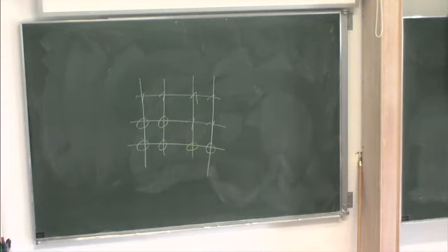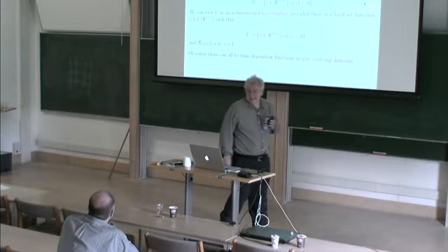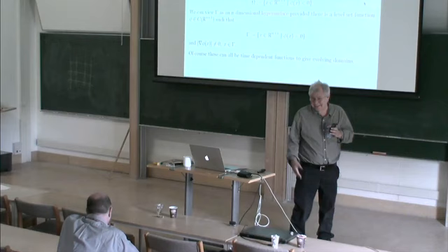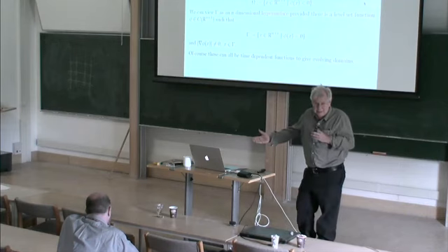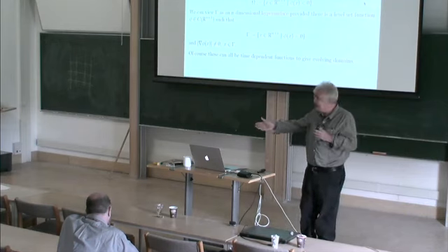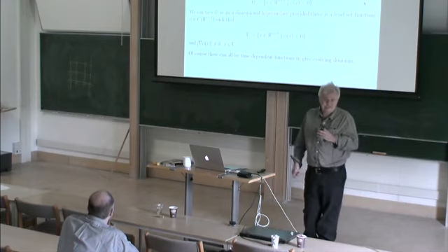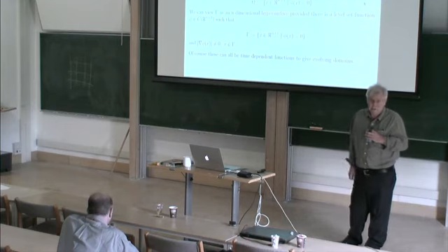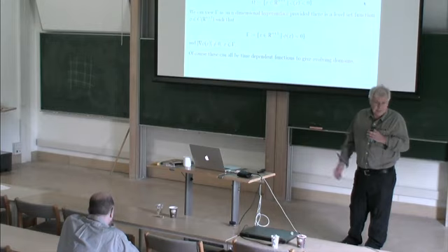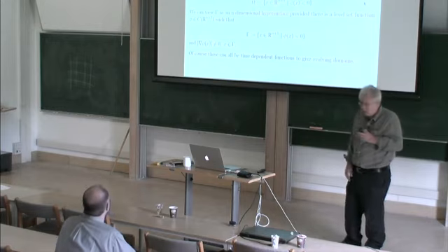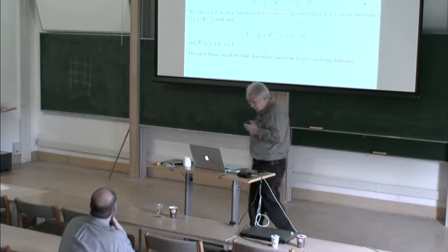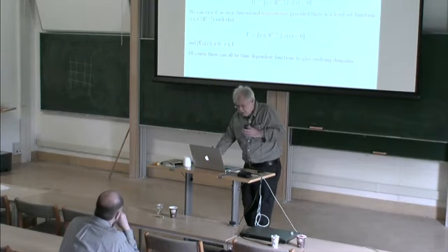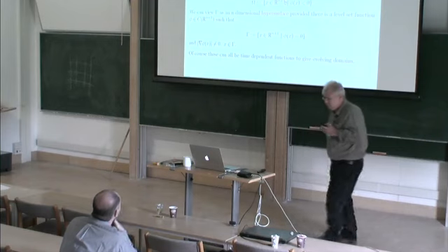And then you have to calculate how much fluid there is in each one of those cells. And that's volume in that cell, that's typical. This method is still used. The method is kind of in legacy software, and that's why it's still used. But there it is. You can use that method. You can also use a level set function.